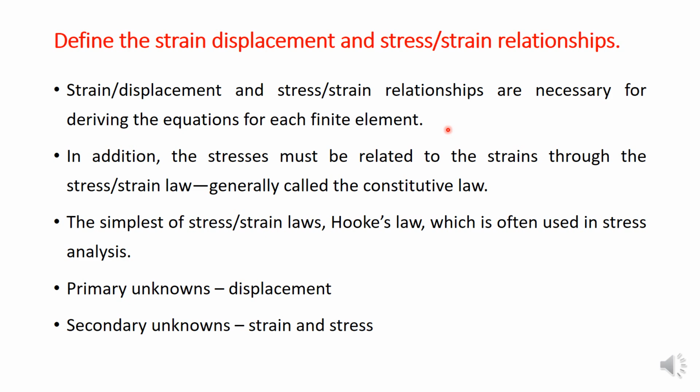In addition, the stresses must be related to the strains through a stress strain law, generally called the constitutive law. The ability to define the material behavior accurately is most important in obtaining acceptable results. The simplest stress strain law often used in stress analysis is sigma x equal to E into epsilon x, where E is the modulus of elasticity.